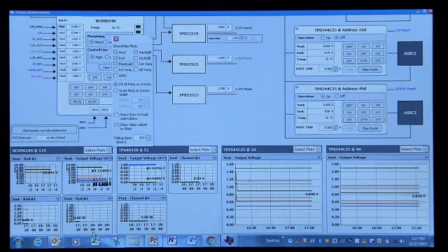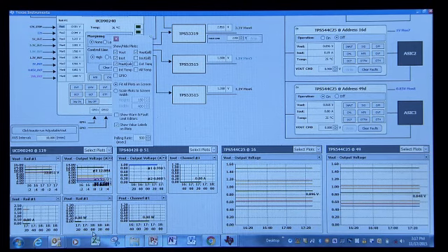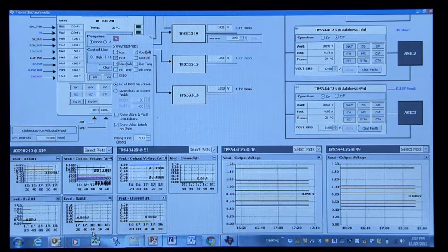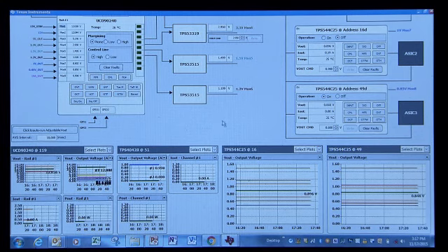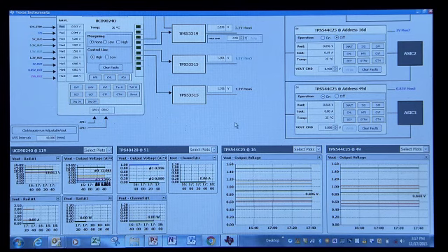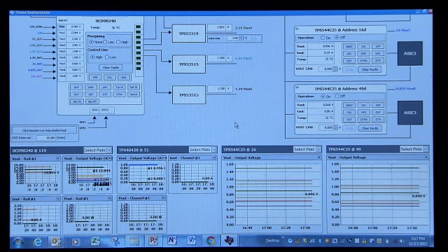This is a full Ethernet switch PMBus demo where the UCD90240 manages the analog voltage regulators and also implements monitoring of the voltage, current, and temperature. And this demo also includes the PMBus regulators, TPS544C25 30 amp with integrated FETs, as well as the TPS40428 dual output or dual phase PMBus buck controller.